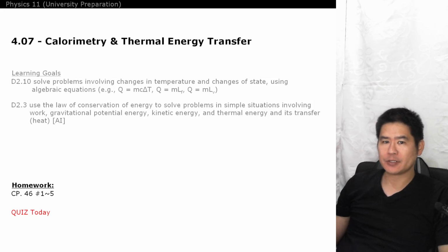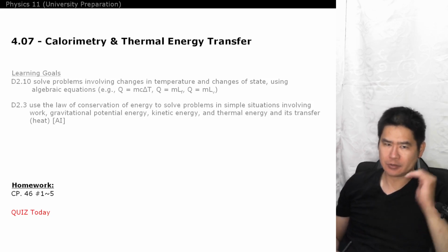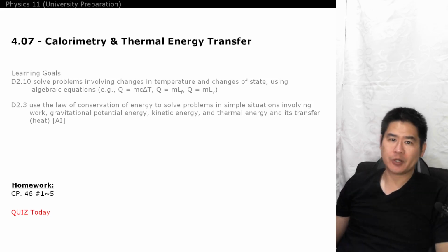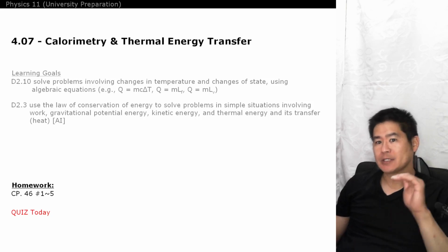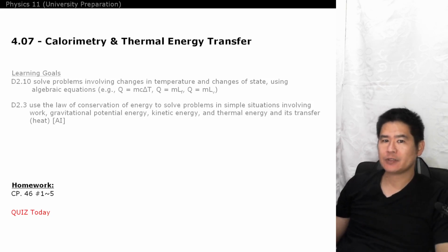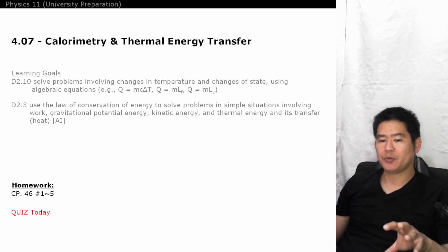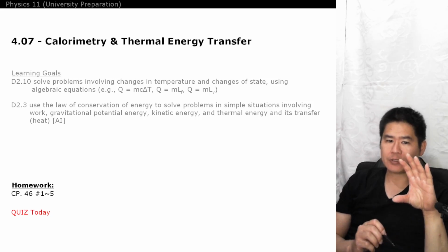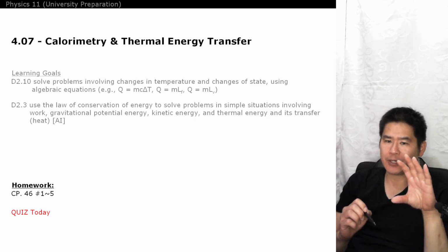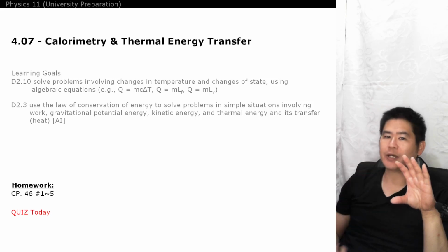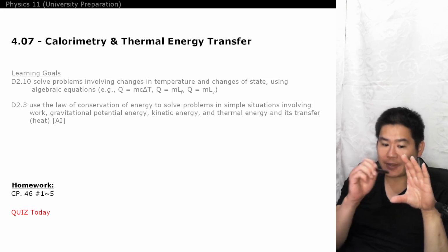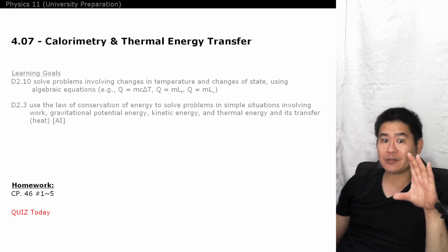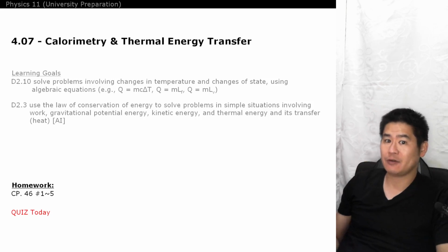How do you get to 100 degrees Celsius? As long as you have pure water and it's not a rainy day or a super sunny day, so you're at regular ocean level air pressure at 101.3 kilopascals, then the water will boil and stay there at 100 degrees Celsius. So that's how you calibrate a thermometer. Put it in ice water, let it sit, put a marking down here. Boil that same solution now, let the temperature stabilize. As long as you're not in the mountains, it will stabilize at 100 degrees Celsius. Divide that by 100, and now you've got something measured in degrees, portions out of 100.